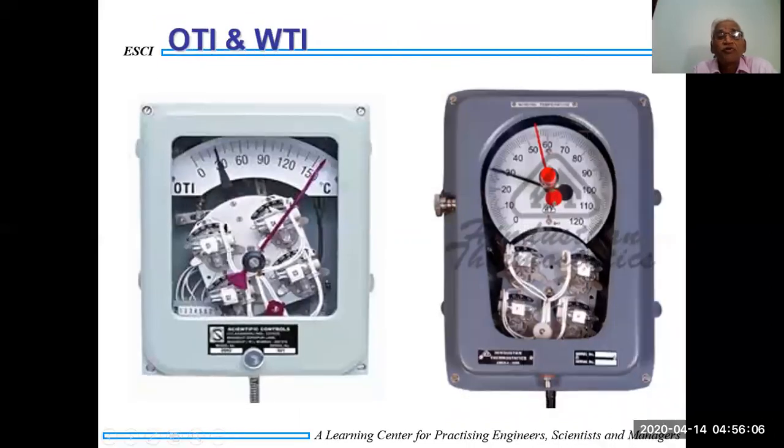And these are the two photographs you can see. This is one, this is one. In this, there are four numbers. Oil temperature indicator: how it is used is, when you have a fan connected there, the fan will come into operation the moment the temperature crosses around 70 degrees centigrade, and runs, so the transformer oil temperature comes down.